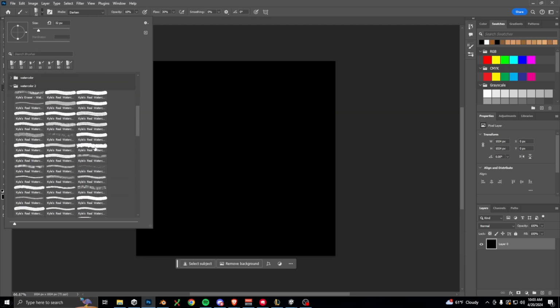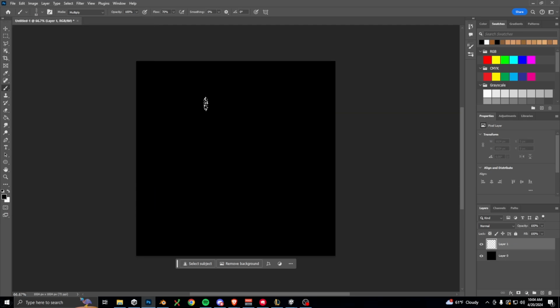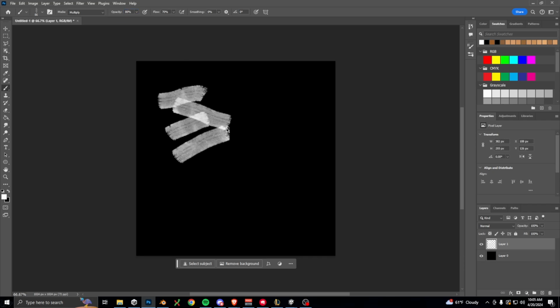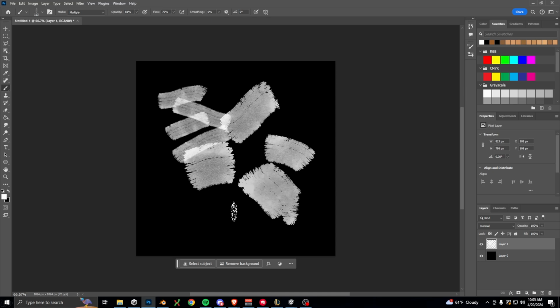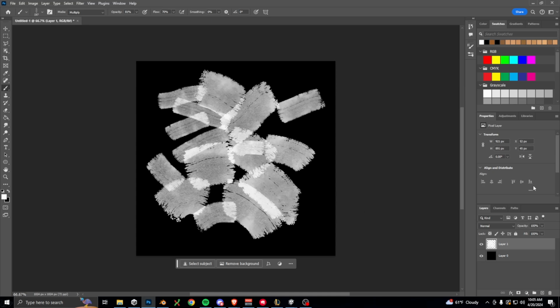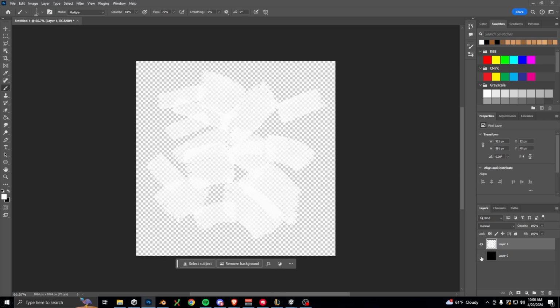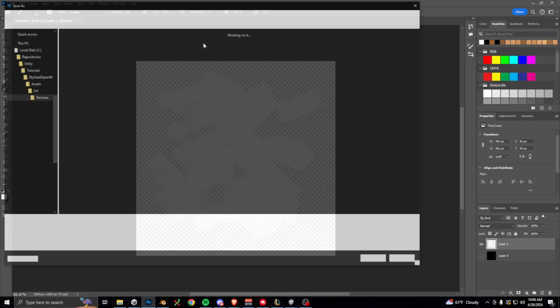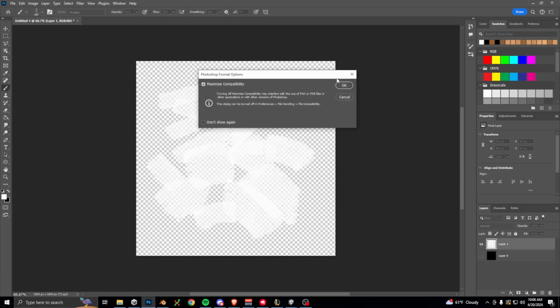All right, so now I'm selecting my brush, and one useful tip here is that you can use the command Alt right click, then drag to resize your brush. So I'll just be painting on some leaf-like patches. I'll select an opacity of 80% so our leaves are a bit transparent in some of the places. As I'm drawing in here, I'm going for this hand-painted look, so even though things don't exactly look like leaves, that's totally fine. So that's all we really got to do. Go ahead and hide the background and save this. I'll put it in our textures folder and name it Leaf Text 1.